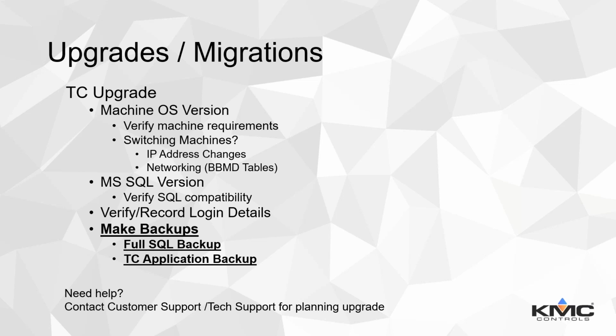And the one thing I can't focus on enough is to make backups. Make backups of your application. Go into SQL Management Studio and make a full SQL database backup beforehand. Go into TotalControl, where we have backup application features to make a full TotalControl instance backup.